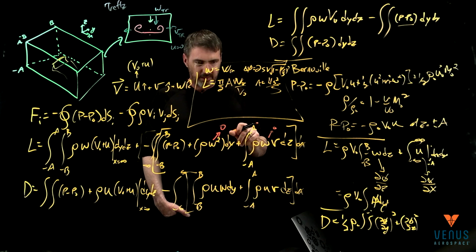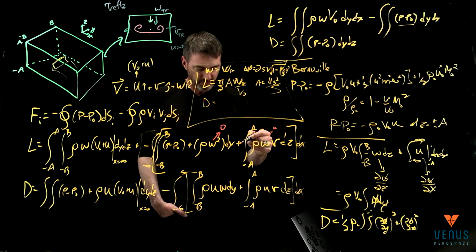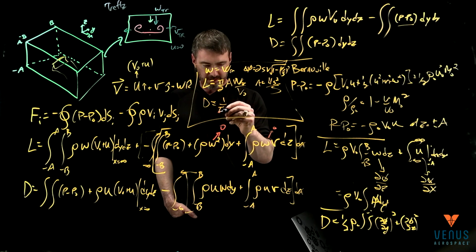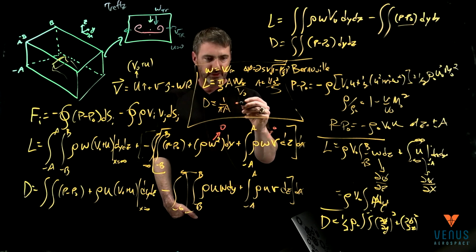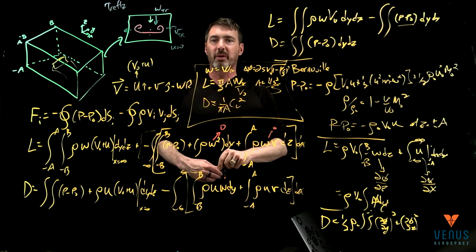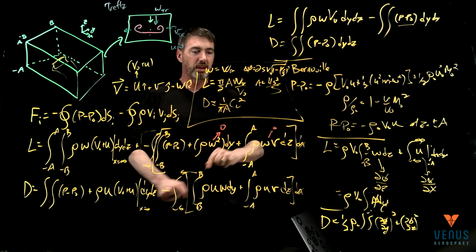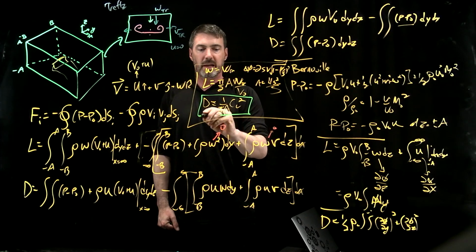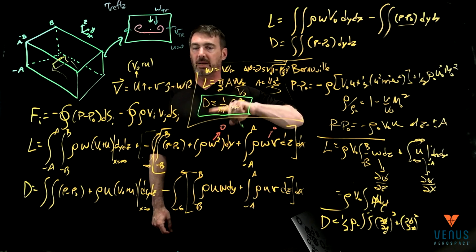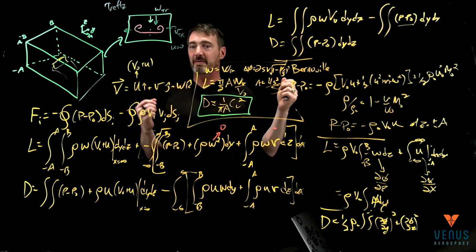And then what's neat is you then work through the drag. It's out of room. We'll just go to the punchline. You can do this same thing for the drag, and you get 1 over pi times aspect ratio times lift squared. So with my head barely poking over here at all the equations, I'm going to foot stomp on that and say, look at this. We actually, through potential theory, showed how the drag scales with lift squared. This is a 3-dimensional effect. It is not a viscous effect.